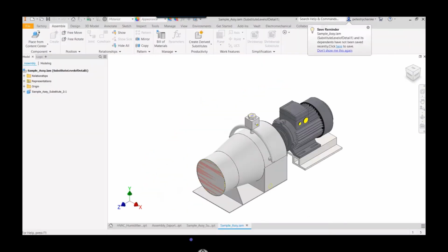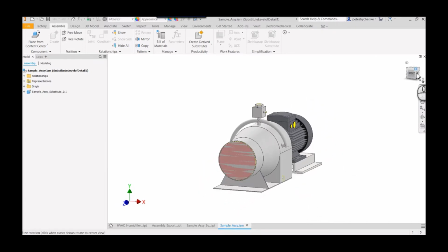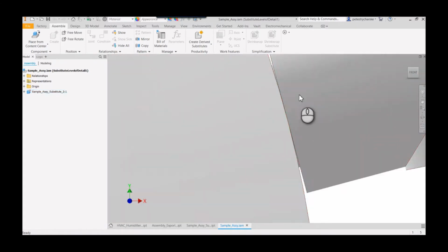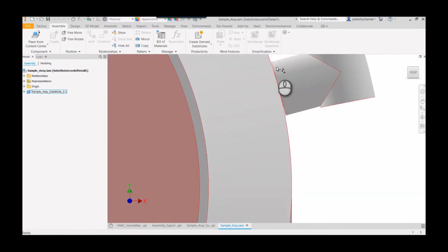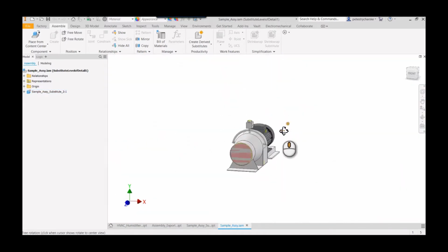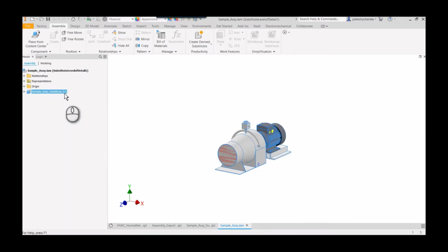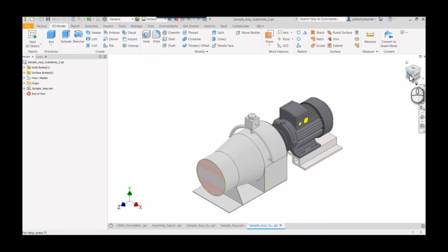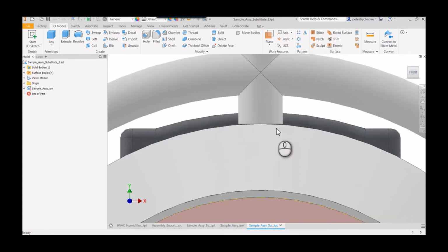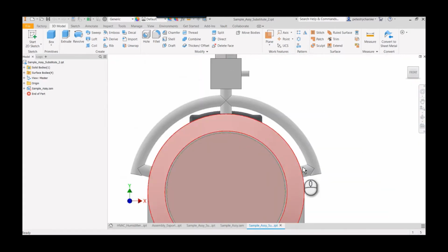What I've discovered with the help of Johnson from Autodesk is that Revit gets a little bit picky sometimes because it'll see these little gaps, and it doesn't do well with those gaps, so it doesn't know how to resolve that surface. The process I'm using utilizes what's called a shrink wrap substitute. In the shrink wrap substitute, this is the actual component that gets published. It's got the tangency like I want, but it can't handle those surfaces.